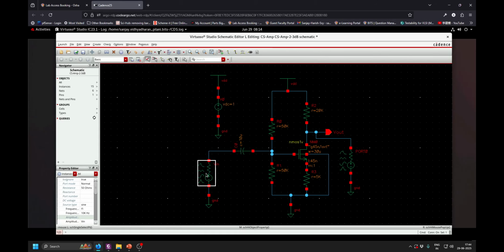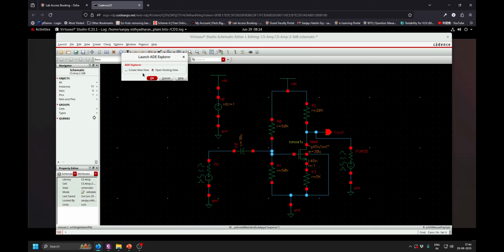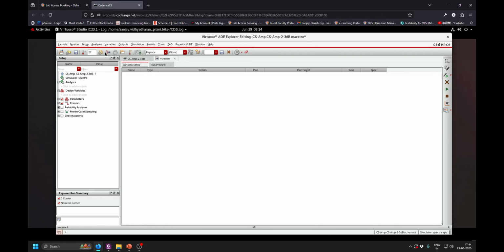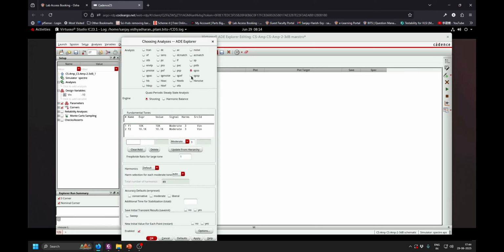So that's done. Then I go to Launch, Explorer, create new. Yes. Right. So variables, copy from cell view. So I got this Vin out here. I'm giving a default of -10. Analysis, choose, and this time I am going to choose QPSS.